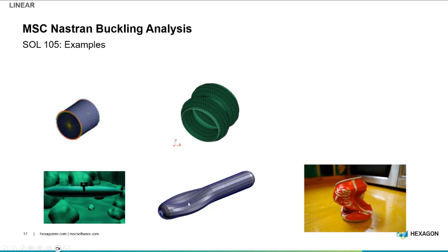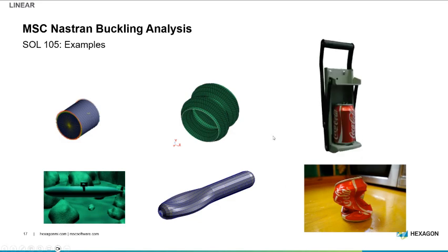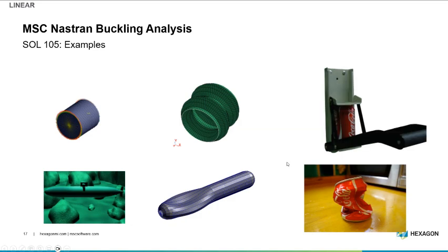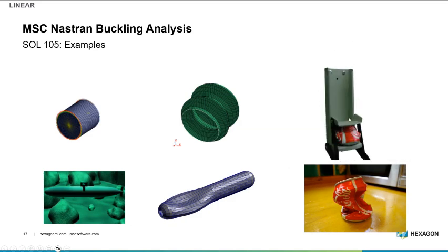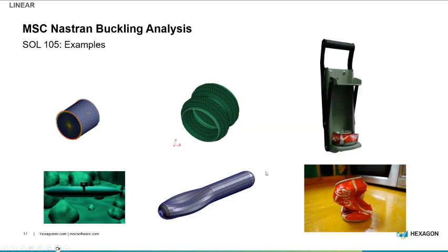Now, this is something typical on thin wall structure or beams with a compressive load, for example. By no means exclusively. Here's an example of a Coke can that is buckled, and it's plastically deformed into that buckled shape. So it's possible to model effectively something like this using a buckling analysis, or even a nonlinear analysis with plasticity, you can get to that same final state.